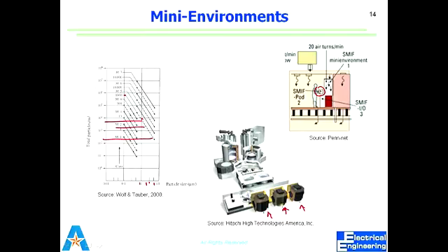Then on the hood, they have these markers, maybe by the manufacturer, maybe written by the staff, where they'll put an arrow and they'll say the hood should not be opened above this. The hood is a window which can go up and down, and it has glass doors which can slide side to side. You should not move it above this, because if you do that, the air is coming out of the hood as well, and you don't want that. So those are mini environments that we want to maintain, where within the hood we want to maintain the flow of air.